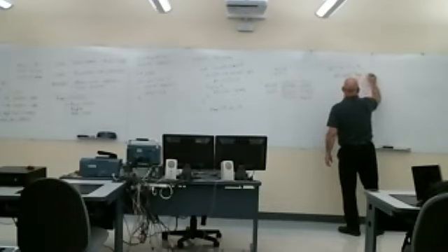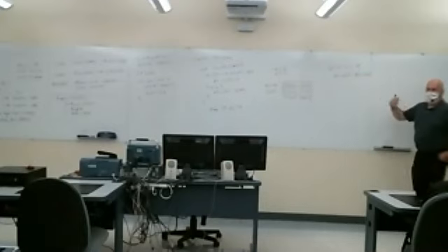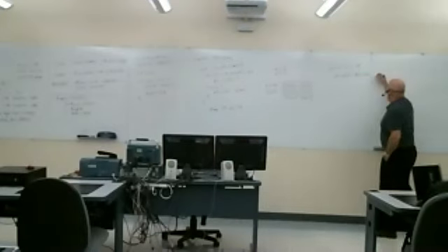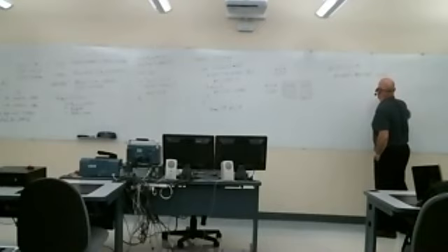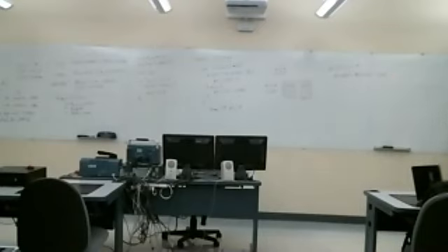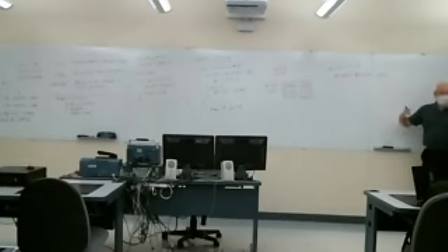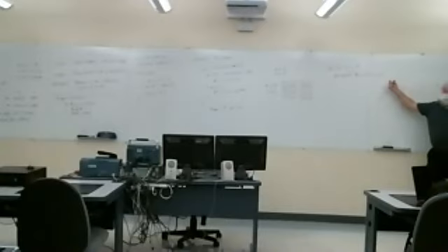what you would typically do is read P4 out, read that register value, and then OR that with 0x, what did I say, 40. So that's another common operation. Now, what does ORing with 0 do? A ORed with 0, what is that always equal to? It's equal to A always. 1 ORed with 0 is 1, 0 ORed with 0 is 0. It doesn't matter what A is, we get A back. So ORing with 0 is not going to change any of those values.